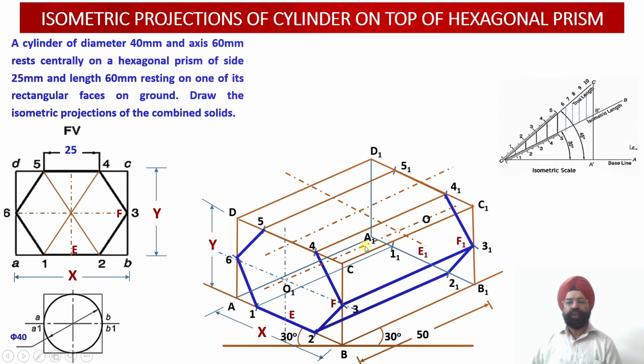My cylinder is going to overshoot this particular surface. That is, my cylinder will be drawn over here. Please check, I will be drawing a cylinder. If this edge is equal to 40, then both of these are going to match. If my 40 millimeter is shorter than CD, the cylinder will be drawn within this portion. If my 40 millimeter exceeds CD, then my cylinder is going to be drawn even beyond this particular thing.